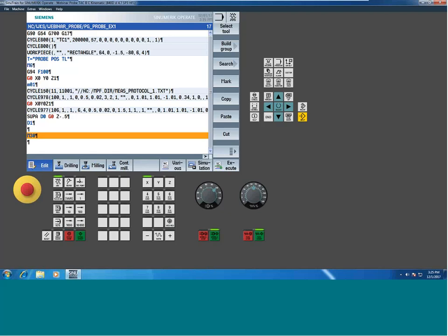So normally what I do there is measure a feature, grab the OVR, because a lot of times the next cycle will write over that OVR. So grab it, save it to an R variable, go measure something else, save it to an R variable, then make my calculation.